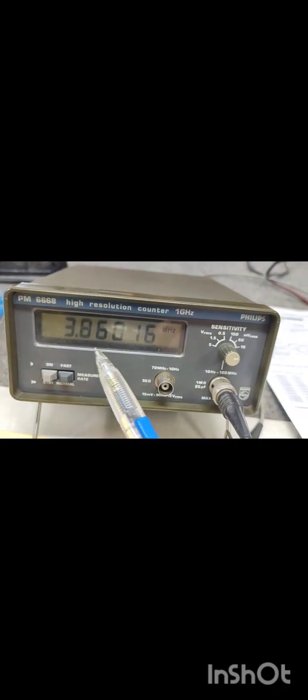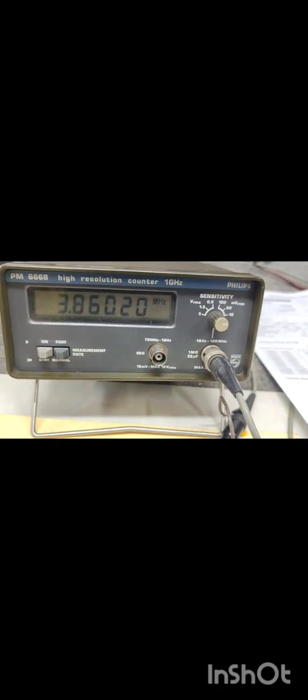You can see on my measuring instrument, which is fed into the frequency counter, that it shows 3.860 whatever. Now there is a discrepancy, and that is a normal thing for these ceramic resonators, to differ by 100 or 200 kilohertz and so on, as I've already mentioned earlier, due to the requirements where they are used.